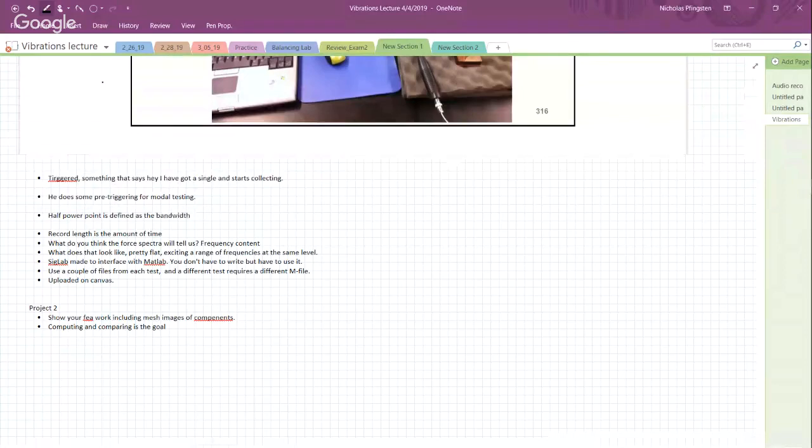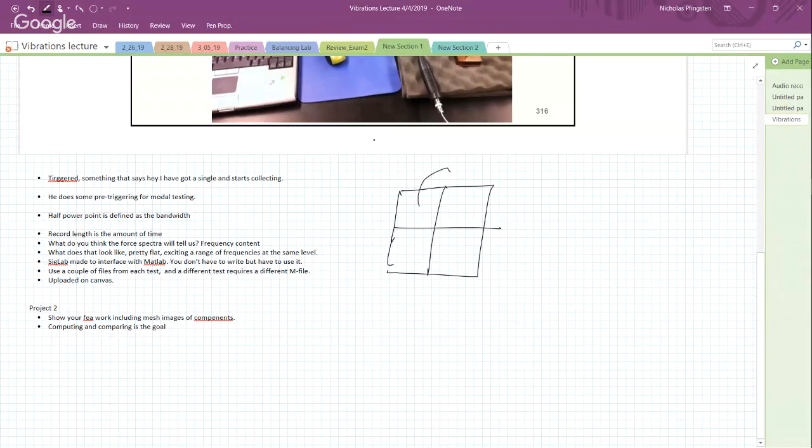The top left quadrant is my channel setup. And you can see right here it displays channel 2, but I have the option, of course, to pick channel 1 and channel 2. The number below the channel number is a voltage level.